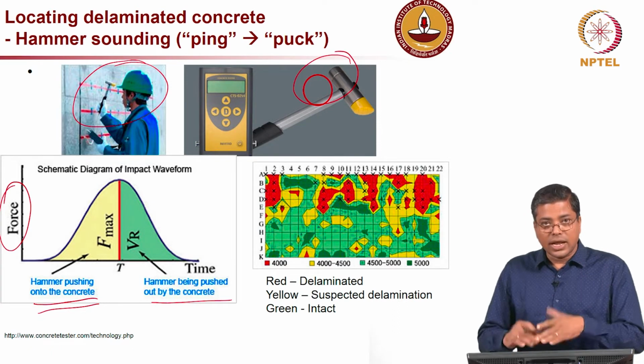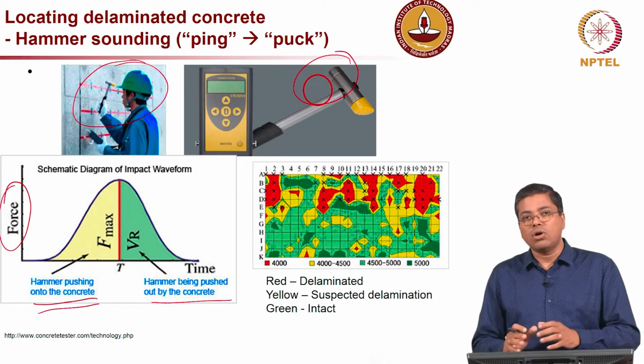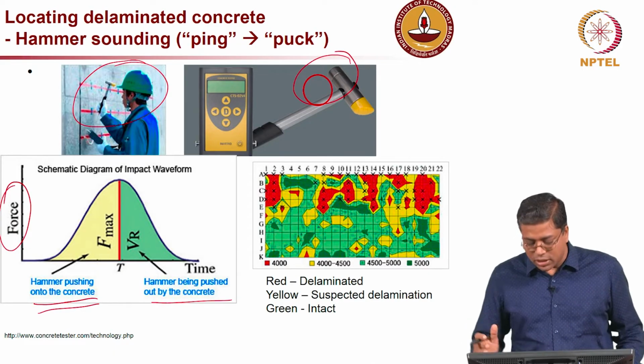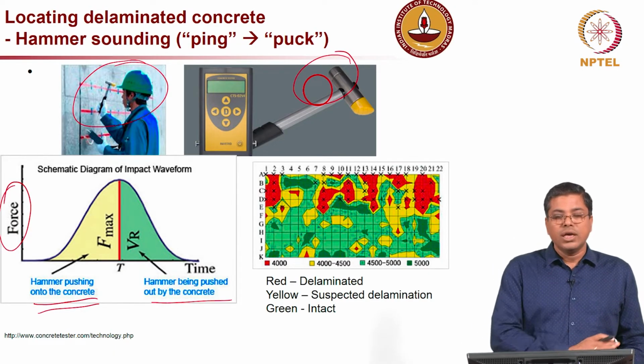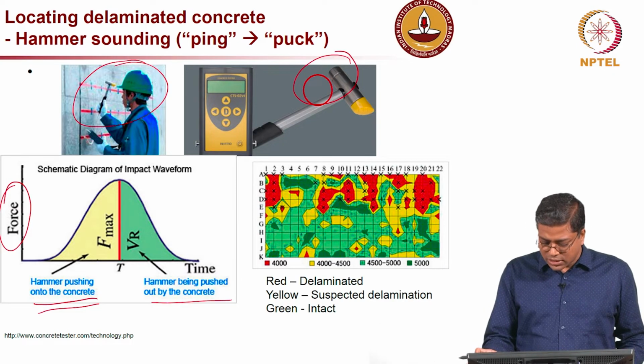And then the next step could be to go and do a detailed inspection on the delaminated region, or you can remove the delaminated region alone instead of removing the entire concrete surface. So, that is the idea here.